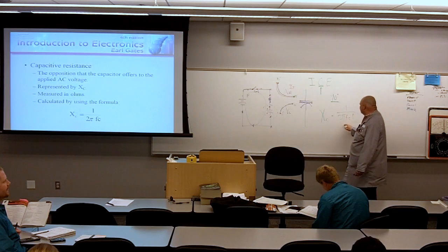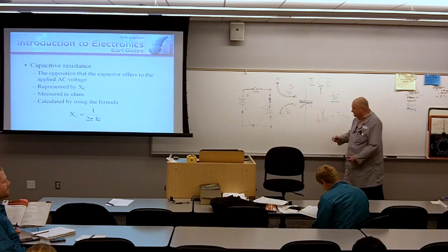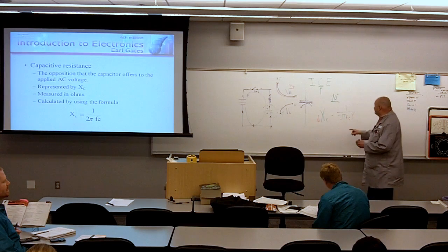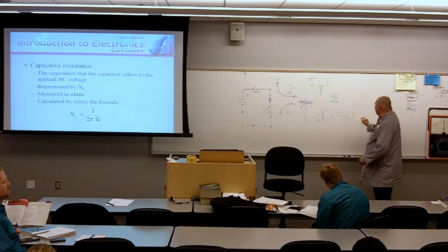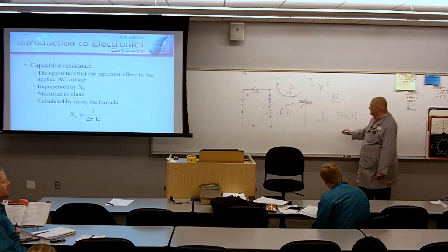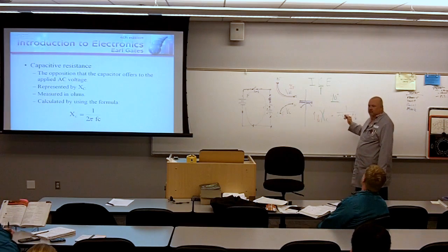So these two numbers are not going to change. If f increases, x sub c is going to decrease. If c increases, x sub c is going to decrease. If f or c decreases, x sub c is going to increase. We call this an inverse proportional relationship.